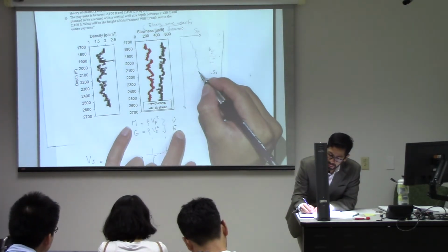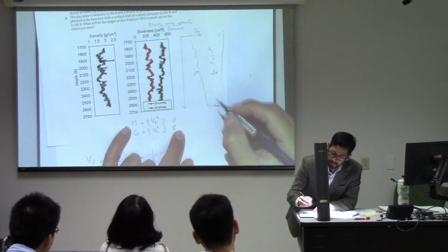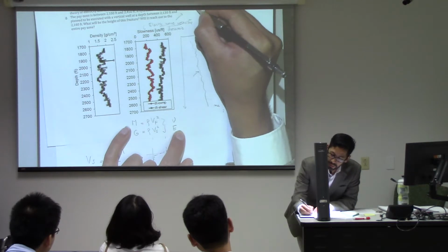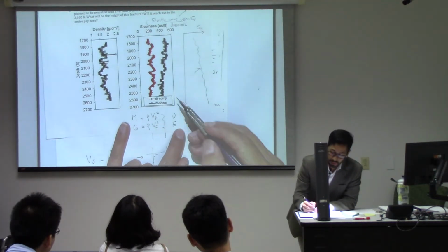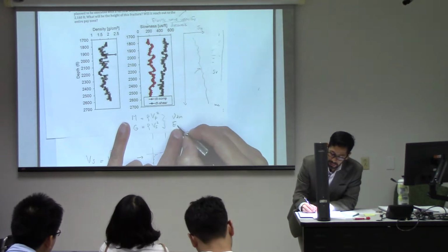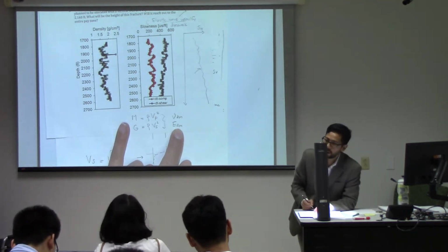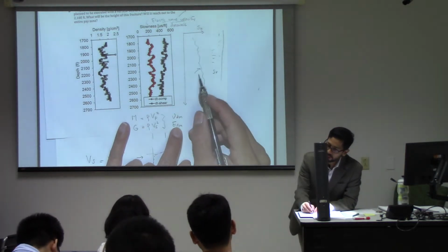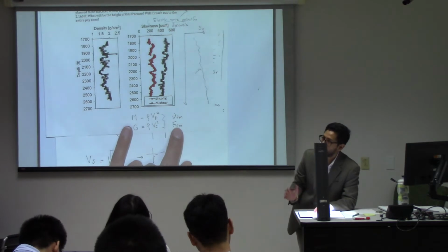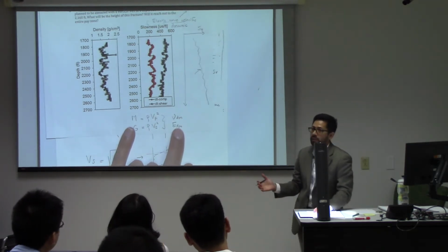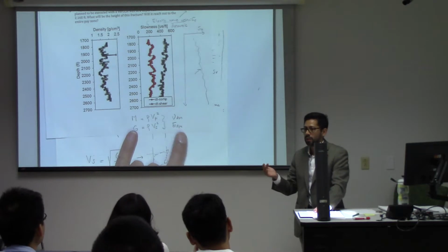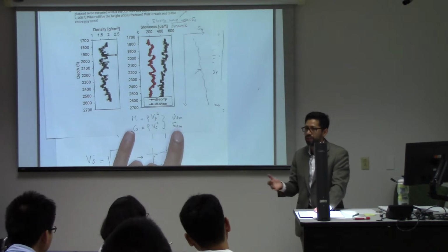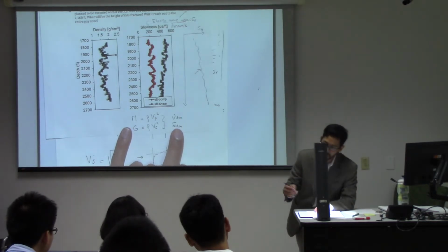The Young modulus that you get from here is going to be a dynamic Poisson ratio and a dynamic Young modulus because they are determined from waves. However, in order to compute these stresses that build up over thousands of years, or sometimes if you want to compute the stress change during the course of reservoir depletion or completion, a few days, a few years, it's also not going to be the same.